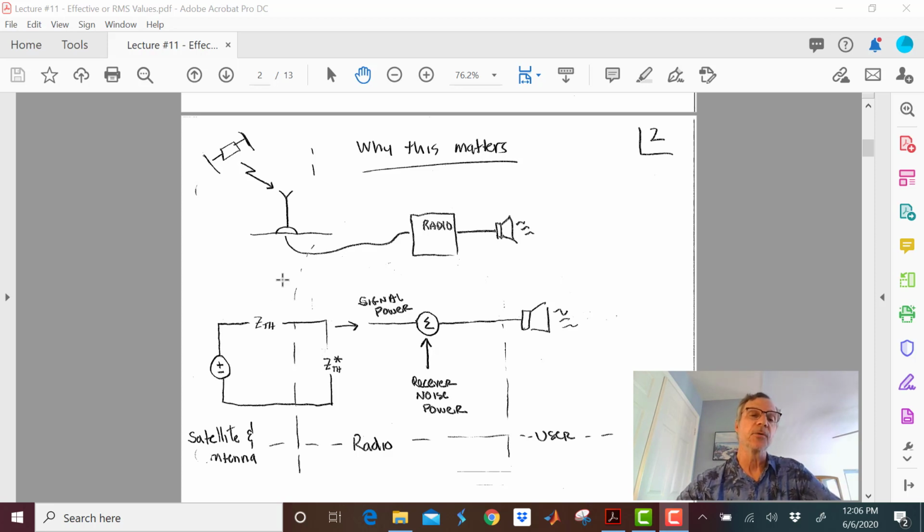So what I do is I say, okay, satellite and antenna, what you look like is a Thevenin source. So you can see I drew my little dotted line. It's kind of hard to see, but it starts here and it goes right through that cable, and then I show it right here. That satellite transmitter, the ether that it goes through, the geometrical shape of that antenna, etc. At the end of the day, it's just a Thevenin source.